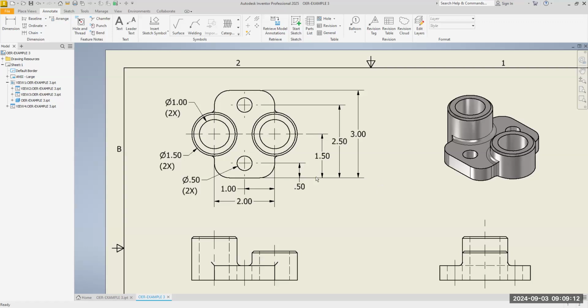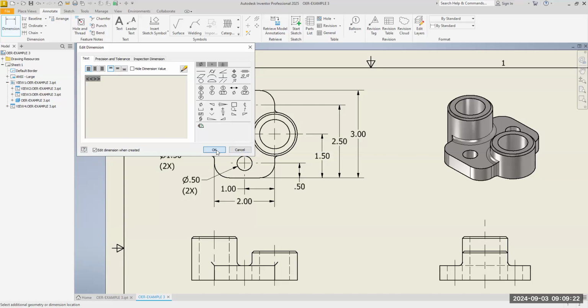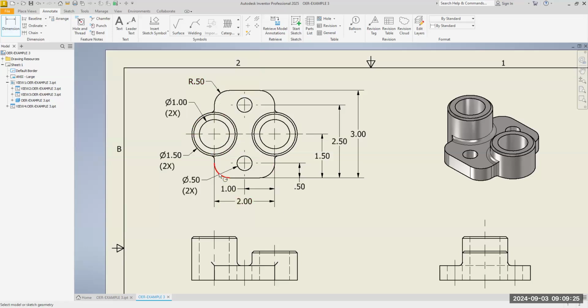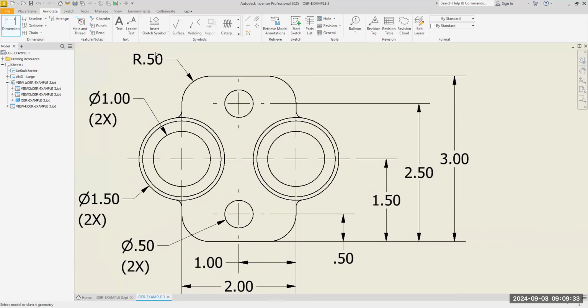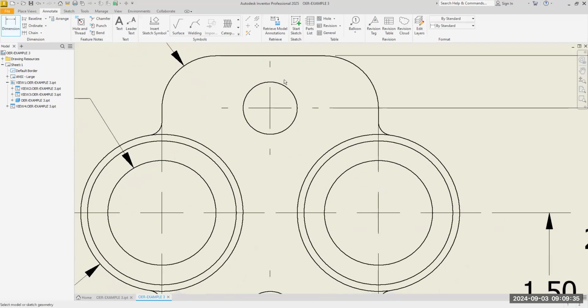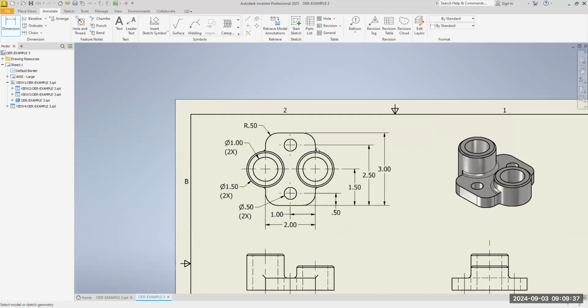I don't have around this rounded corner here. It needs to be dimensioned. Look, I'm not going to do that 4 times. It's understood that if no other dimensions are added, all those are 0.5. We also have fillets.